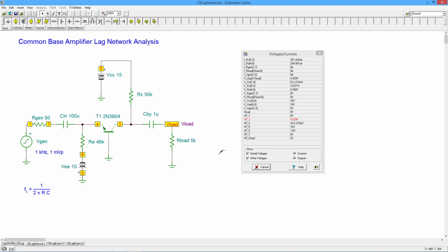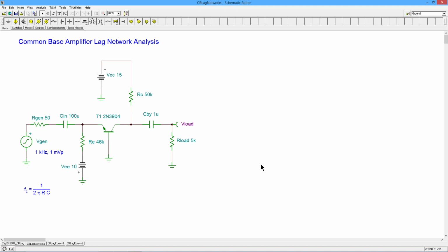No big deal there. Now, we could take the difference between these two currents, the emitter and the collector currents. That's the base current, right? Which you can see is going to be 2.6-ish or something like that, microamps. So if we divide that into the collector current, we'll get a beta. Beta turns out to be around 77. So not a super high beta.